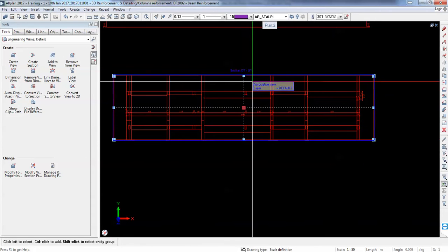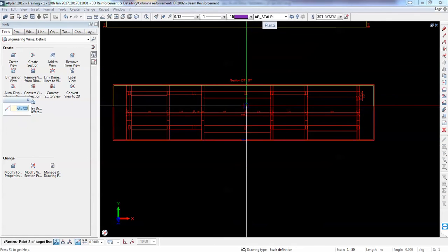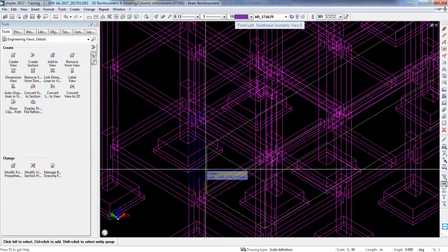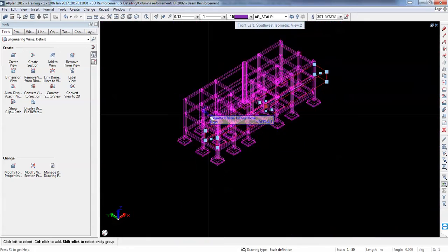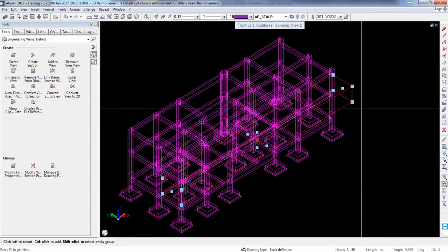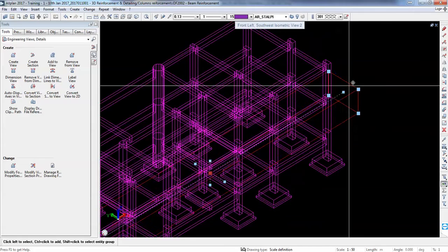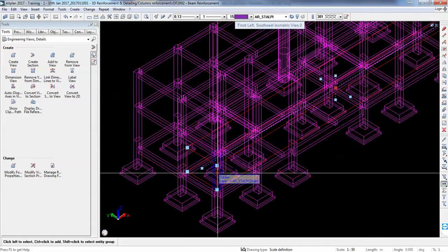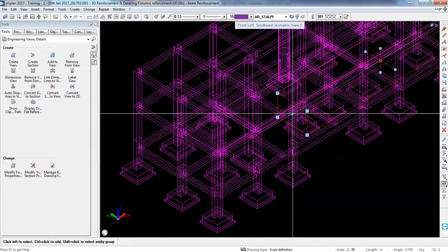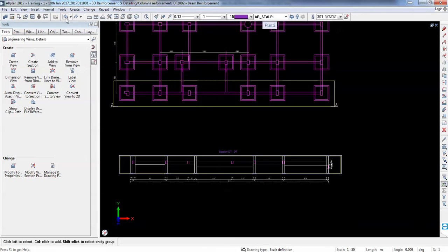So it's quite easy to do this. Anything that is detailed here is actually within a yellow box. So if you see here, this is a box that contains whatever I detail. So basically, this is the main idea behind the associative views. You select the objects that you like to see, you select the direction of visualization, and then you define this 3D box in which you see elements. Any modification of this box, even from here, will affect the result. So basically this is how you control what you see.